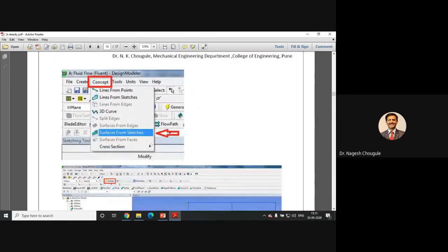So we are interested in creating a surface with the help of wireframe entities. I have drawn only a rectangle, and I want to convert it, as you can see in surface from sketch. Here we are applying the bottom up approach. I created only 2D geometry initially, and now I am converting it into a surface model. If required, I will then create a solid model.